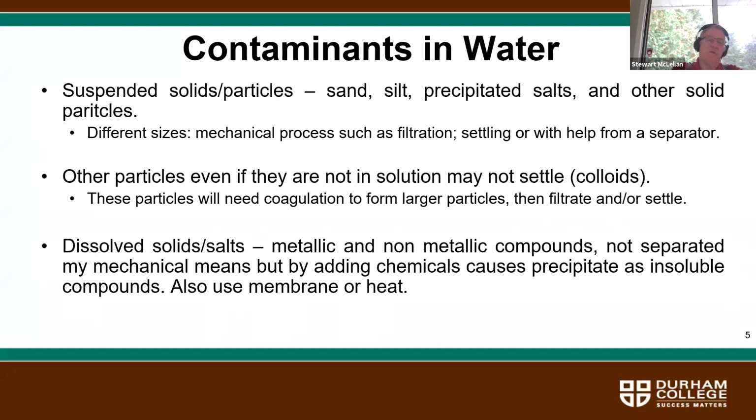In the case of dissolved metals, they will precipitate them using a metal hydroxide reaction, which converts the dissolved solids into insoluble materials, which are then precipitated. You can also use membranes or heat to convert the dissolved solids into solid particles.